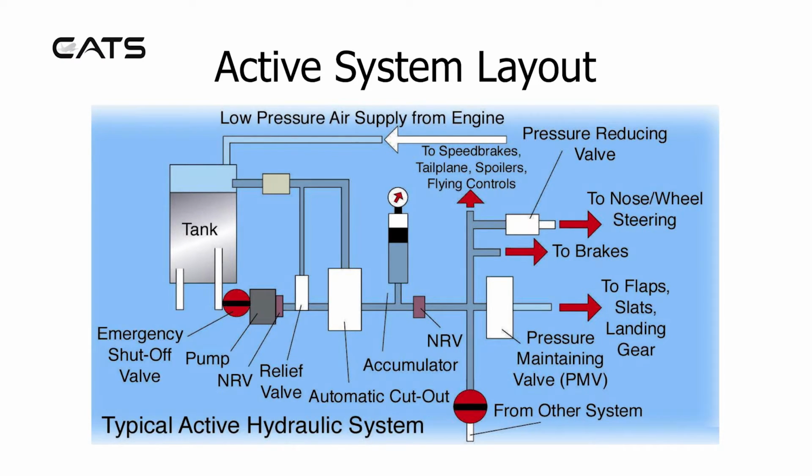After the relief and cut-off valves, there's an accumulator. An accumulator is like a shock absorber. It contains fluid and gas within it with a dividing separator. It serves as a means of preventing surge in the system as an additional reserve of fluid.